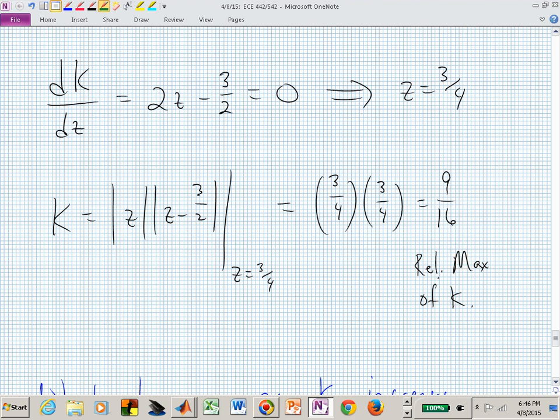It was 2 to get us to 1, and then we keep cranking, and you'll see that it's 3. Well, maybe I'm off. I'm having too many examples, but you can calculate. You see how to calculate the z value and then the gain to get you to the unit circle? And if you cranked up the gain k more than that, you would be unstable. Whew. So we'll pick up at that point on Monday.